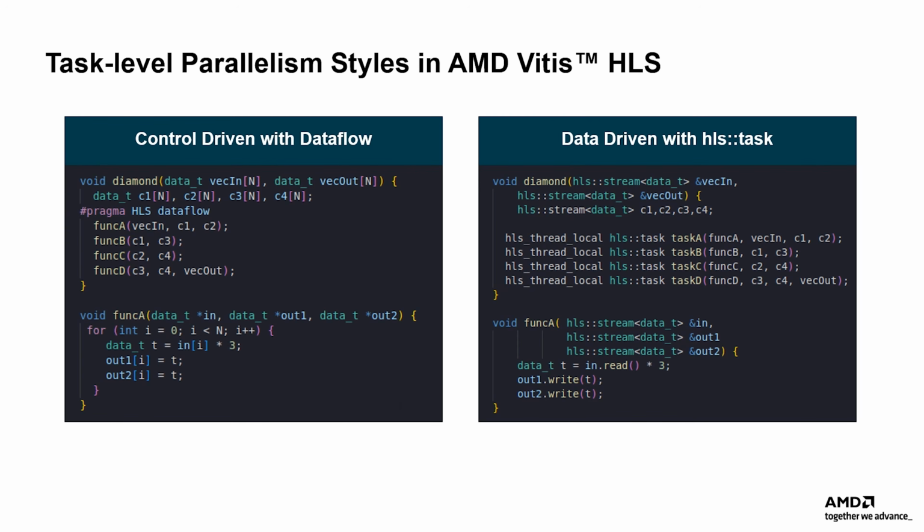If applications are purely data-driven and do not require any interaction with external memory and the functions can execute in parallel with no data dependencies, then the data-driven TLP model is the best fit. You can design a purely data-driven model that is always running, requires no control, and reacts only to data. In this model, the tool-inferred parallelism can be observed in C simulation. These two models can be used independently or together, mixing data-driven and control-driven tasks in a single design to achieve efficient task-level parallel code.